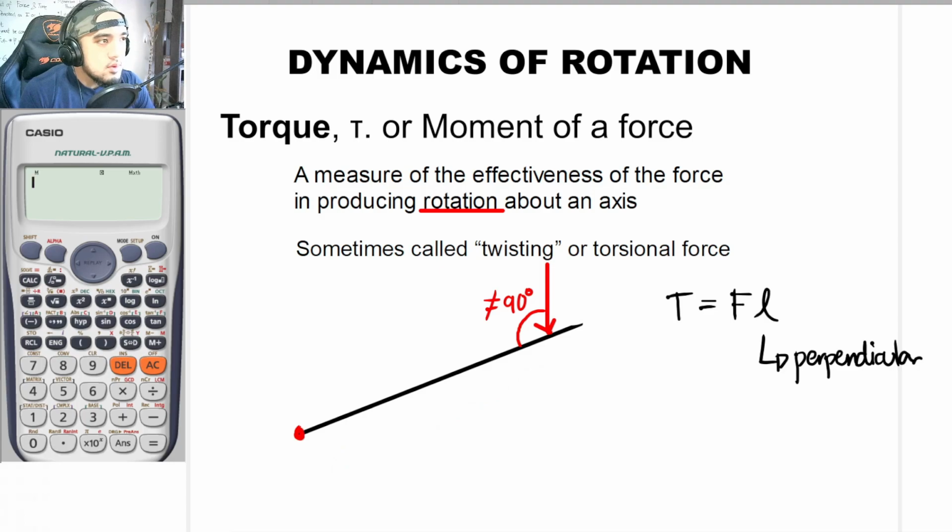What you are going to do is project this downwards, and find a point here that will make it perpendicular. You are searching for that particular position wherein those two lines would be perpendicular. In this case, this is the perpendicular line. If this is 90 degrees, this is your lever arm.